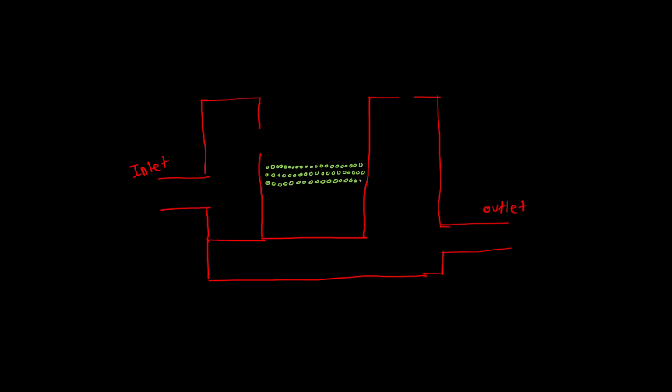The filter media consists of silica sand or the sand particles. Now below these sand particles there is a gravel bed. The gravels are bigger in size. Main purpose is to support the sand bed and to prevent the entry of any sand in the water. And below this gravel bed, there is an arrangement. This we call the under drainage system. It collects the water from this gravel bed.